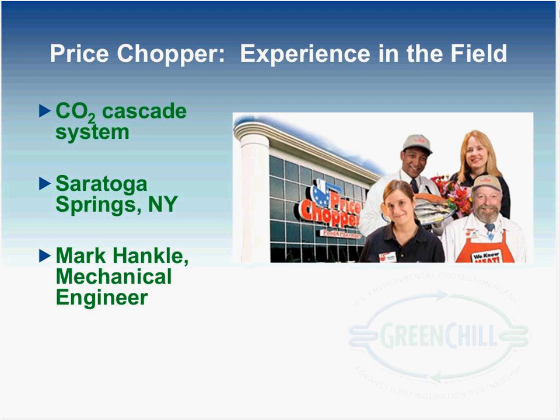And that Wayne was talking about earlier, you can have a single condensing unit that's tied to a generator, a small generator, as opposed to a whole-store generator that's big enough to power the entire refrigeration system. You can have a small 15, 20 kilowatt generator on a small condensing unit. It'll keep that CO2 vessel cold, and you won't lose any of the CO2 charge during a power failure.